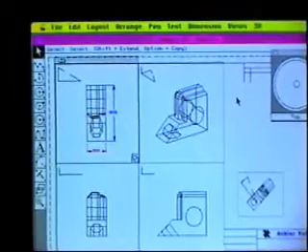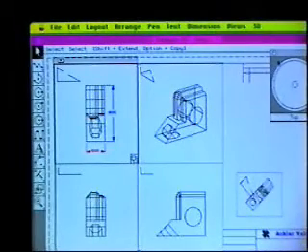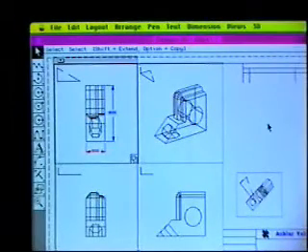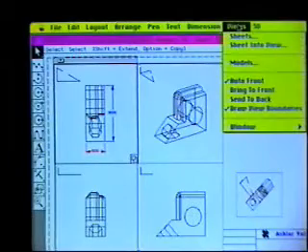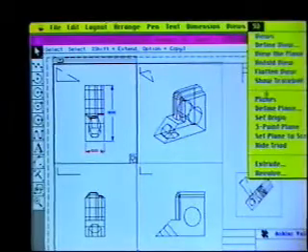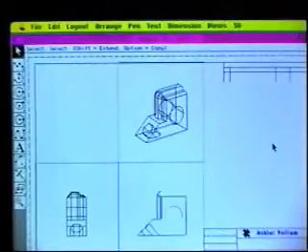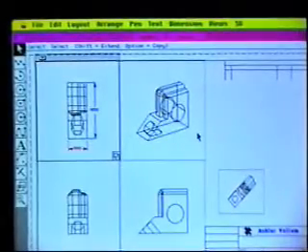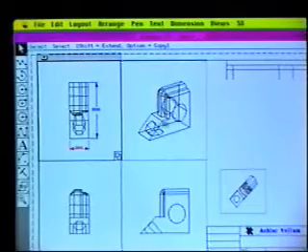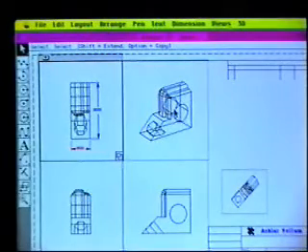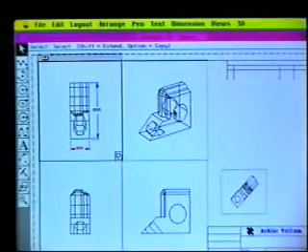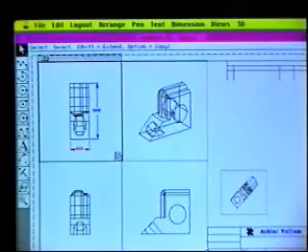And then really the only thing that's left to do is to get ready to print the drawing. I would close everything away, and I would say, first I will go over here and turn off the triad. I will hide the triad. Now when I really want a good finished drawing, I will probably want to make this a hidden line removal or a hidden line drawing. I want to hide the hidden lines.